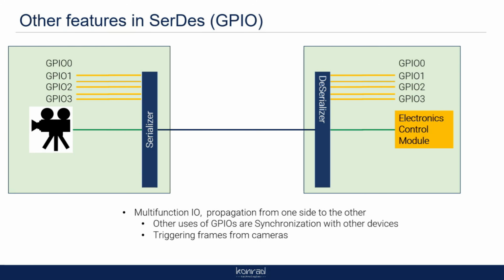Because of how they wanted to angle their cameras, they had two cameras and they wanted two images taken at the exact same instant in time. The camera sensor that they were using had a setting where it would send an image on a high pulse. So we were able to, with the customer, use the GPIOs, and every time we sent a pulse on a GPIO line, because we were using the NI FPGA, we could do it truly in parallel. We would send a pulse over that, and it would give us a pair of images back, taken at the exact same instant because we had the hardware synchronization there. So that's one instance when you could use GPIOs with these.